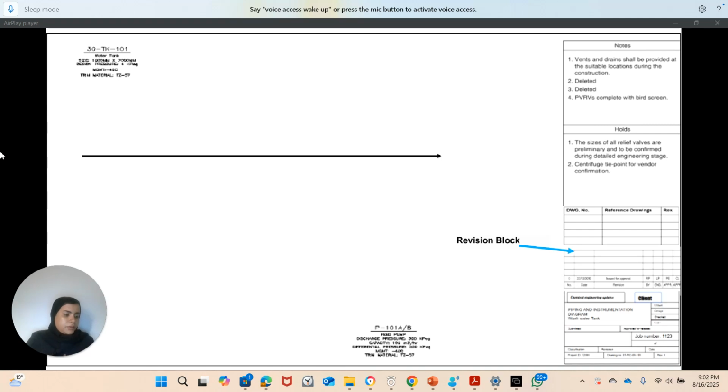Okay. Now let's move to another concept. So here in this section, once you get your go-by sterilized P&ID, you change the different elements. So what happens next? What are the different revisions? First you will start with the first revision, which is issued for review.